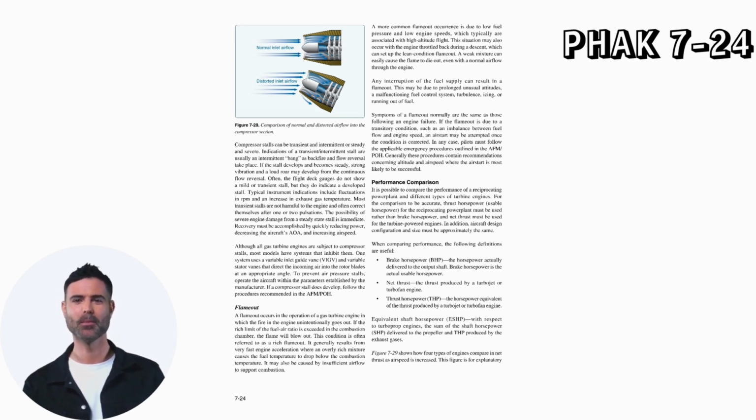Although all gas turbine engines are subject to compressor stalls, most models have systems that inhibit them. 1. System uses a variable inlet guide vane, VIGV, and variable stator vanes that direct the incoming air into the rotor blades at an appropriate angle. To prevent air pressure stalls, operate the aircraft within the parameters established by the manufacturer. If a compressor stall does develop, follow the procedures recommended in the AFM-POH.